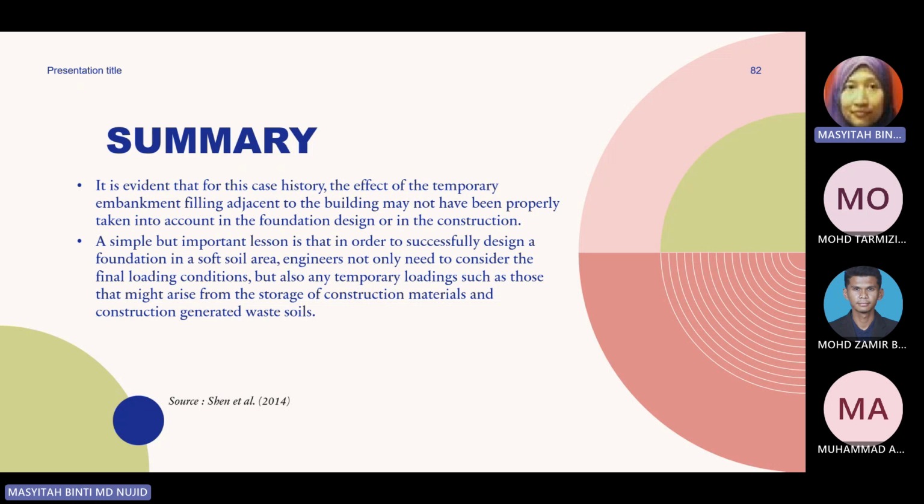It means that once we have done the preliminary investigation, the early step, and we have done the simulation, we know what happens if we calculate the first loading placed this way, and then in the middle suddenly there is additional loading. So you can estimate, simulate or predict by having this kind of simulation. But if you just use hand calculation, usually we estimate for the final one only. We know how much loading we place, and we calculate settlement, for example, or bearing capacity. That is the weakness of hand calculation or approximate methods.